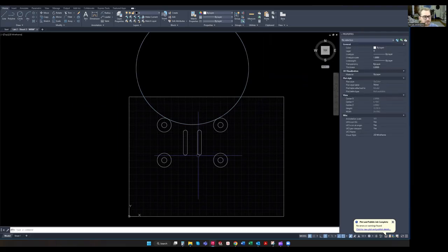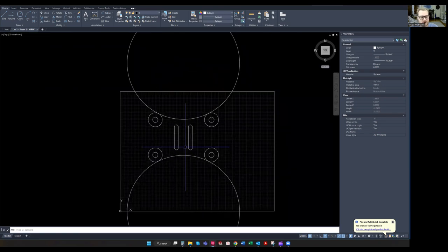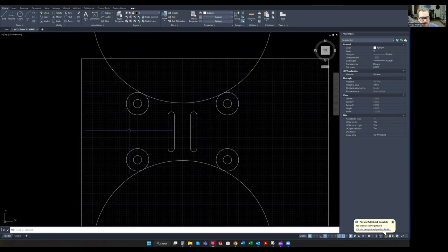And we're going to do that again. Go ahead and grab your tan radius. Click somewhere here, and type 4, enter. Now, 2 more times, we need to do that 2 more times smaller though. Tan radius, grab there, and these are going to be 0.75 inch radius.